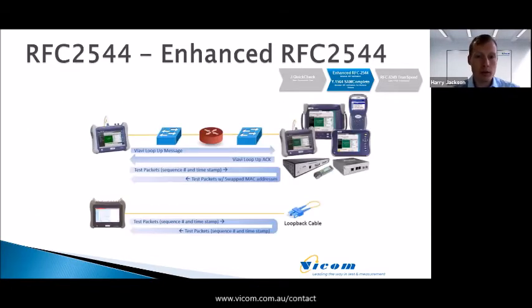So how does an RFC2544 test actually work? Well, as mentioned, you've got your local unit here on the left, and this is the one that we'd be undertaking our testing on. We've then got it connected to our link under test, and on the far end of that link, we've got a loopback device, and that loopback device could be one of dozens of different options.